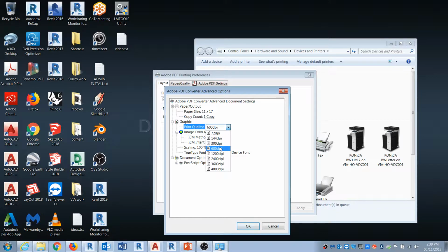The reason is when you're doing a large format print, a lot of print shops have printer devices that print at the fastest DPI they have, especially those black and white OCE or KIP. Their maximum resolution is 600 DPI. Now, if you want to get even faster, I typically set it to the lowest setting, which is 300 DPI.